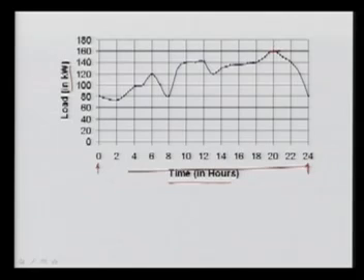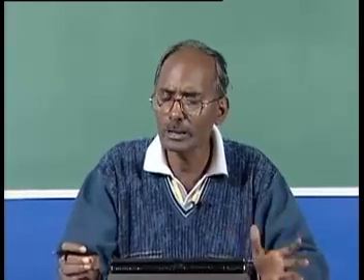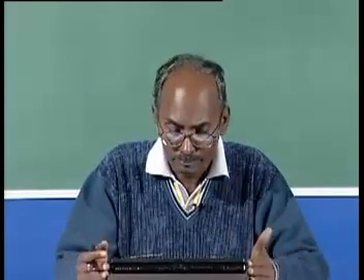It depends upon what type of load you are using. For example, if you are using an industry or commercial organization, your peak will always occur in the office hours. But if the substation is feeding domestic load, normally the peak comes in the evening time, because all the lighting, fans, TV, refrigerator, everything is on. So a particular station normally has a complex load, a mixture of various loads connected.